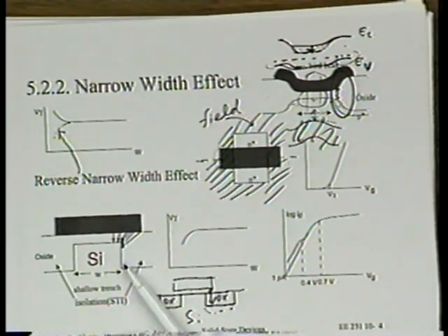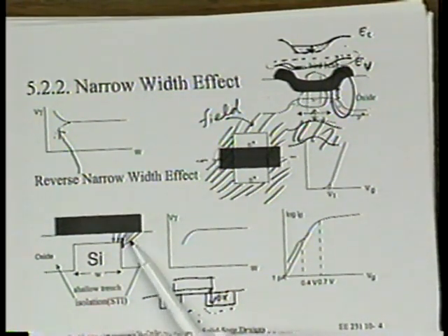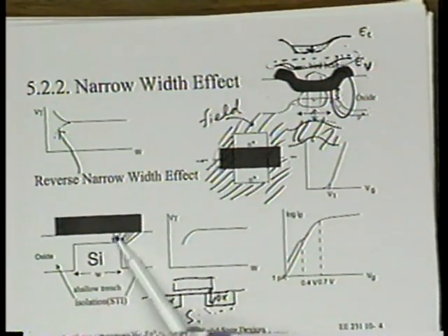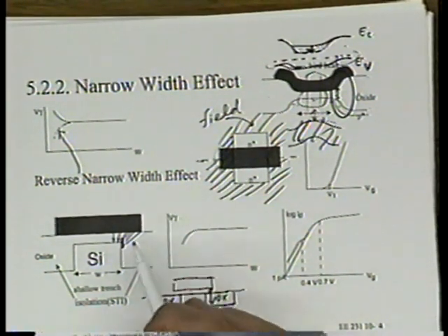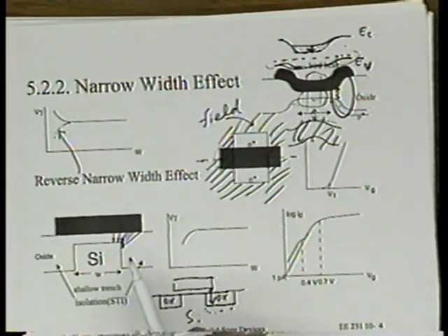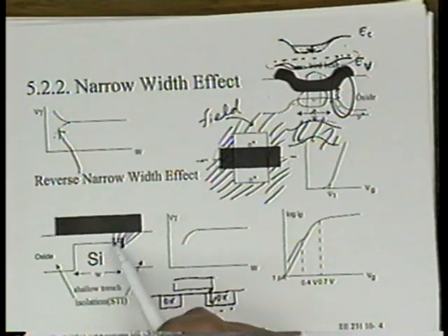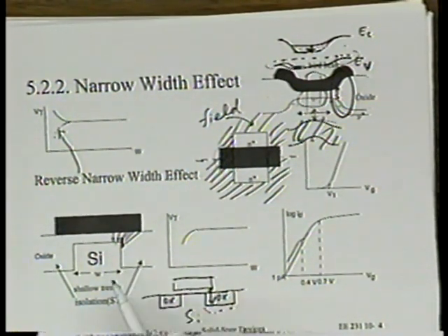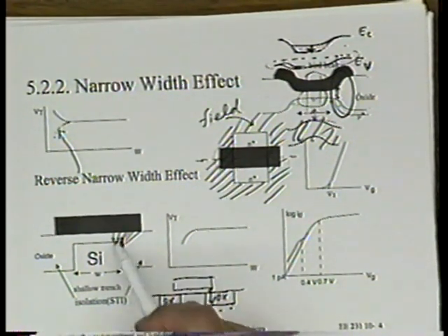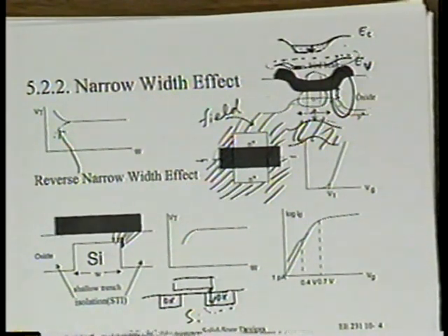It may look strange. You would think that because here the average oxide thickness, if anything, is even thicker than in the middle of the channel. But the fact is that there is a corner effect that causes all the field lines to concentrate on this corner like a lightning rod. And what this does is that it actually increases the capacitance. If you visualize what capacitance is, it means for a given voltage, how much charge is at the surface. That's called capacitance, one concept. And if you also remember, each charge is the source or the ending of a field line. So anytime you have a high concentration of field lines ending at the corner, you know there's a large charge density. It just helps you understand why the effective capacitance is larger.